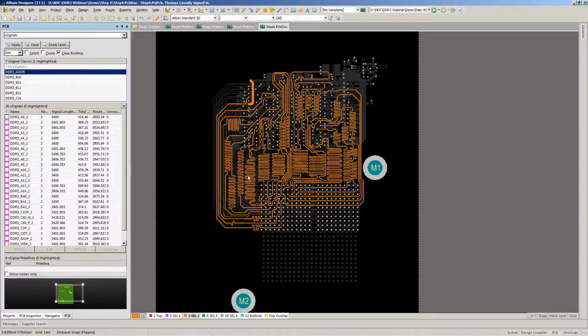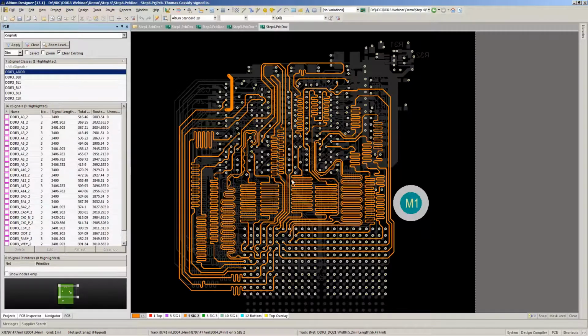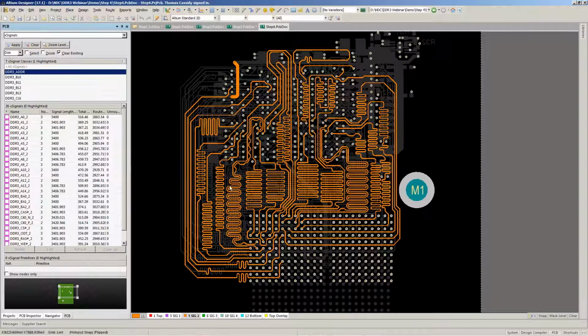You can see, as I said, the data bus lines ended up getting expanded over. I took advantage of Altium's length matching tool to create some of these serpentines, and I'll show you that in a second. But then I also did what I call custom serpentines, where I needed to actually route manually up out of the chip and back down, just because there just wasn't enough room between here. And you may think, oh, this isn't quite following Sean's rule of 2x spacing and the serpentines and whatnot. But as Sean said, you've got to make trade-offs.